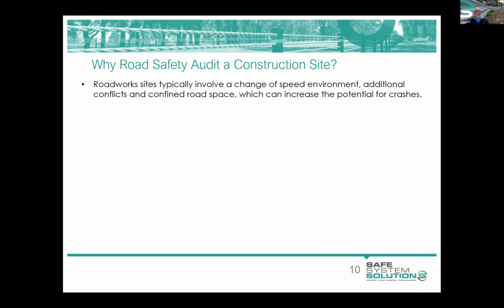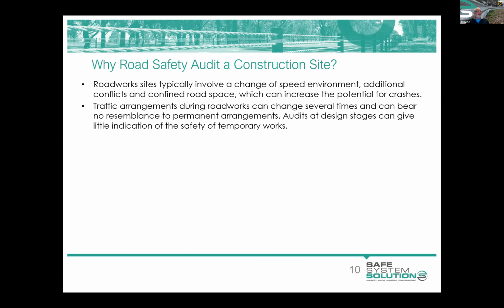And when they get to the end of the job, that they're told that that's it. Thank you very much, we're glad that everything worked well, and this is a speed you can go back up to. That is often one that is typically lost, letting the travelling public know that the roadwork speed limit has finished and that the prevailing speed is now back for them to travel at. So that is one to also look out for when you're undertaking your audits.